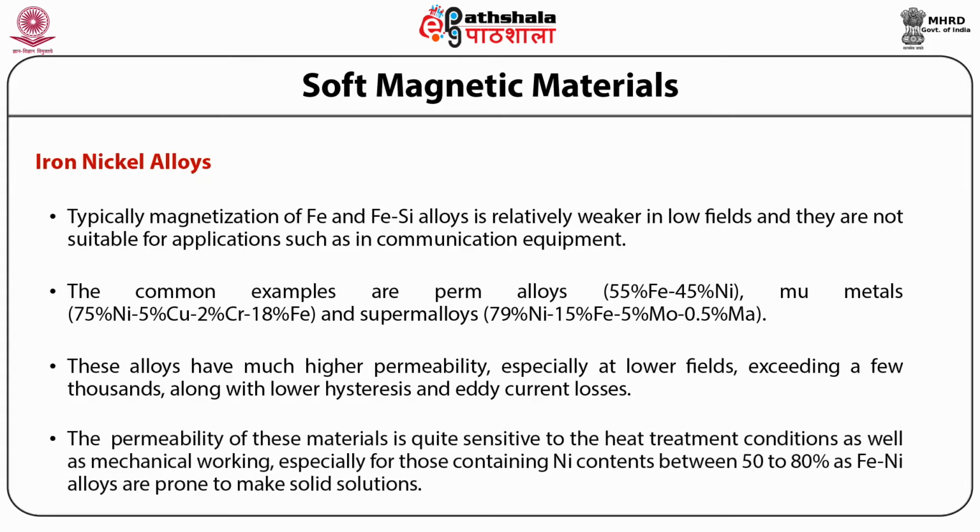The permeability of these materials is quite sensitive to the heat treatment conditions as well as mechanical working, especially for those containing nickel contents between 50 to 80%, as iron nickel alloys are prone to making the solid solution.